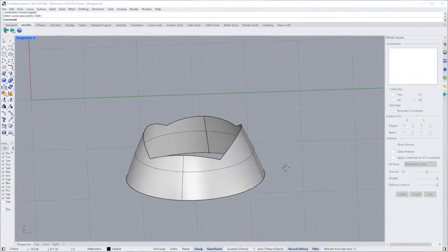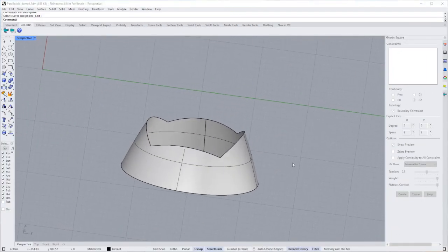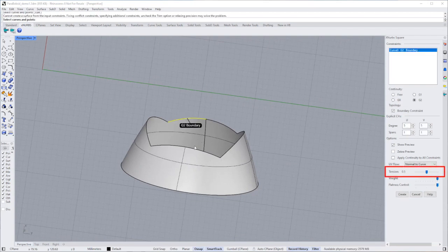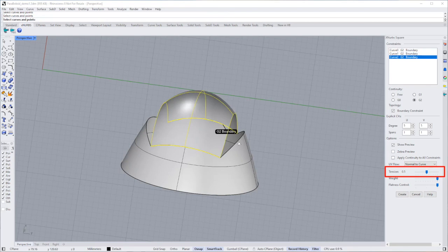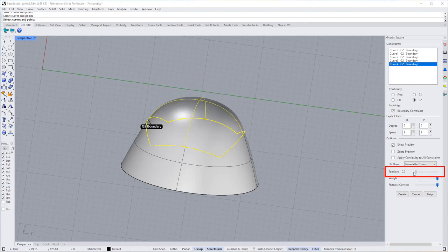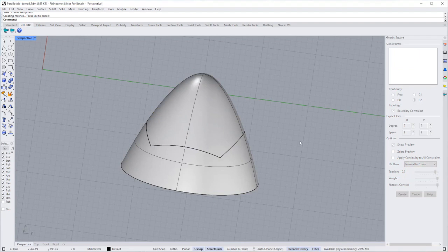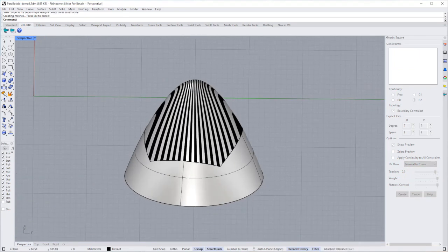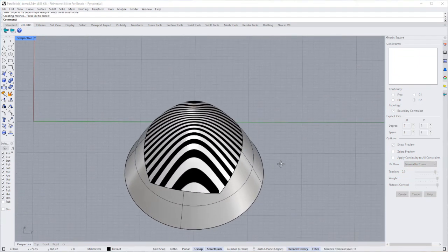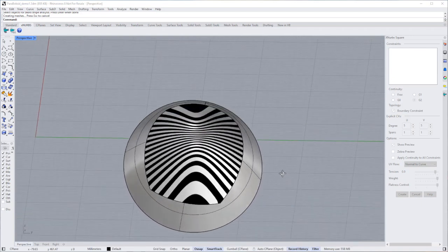Version 7 adds a tension option for square and xNURBS command. When specifying G1 or G2 for an edge, it controls the influence of the edge. You can use it to adjust the shape of the generated surface or the surface bulge. xNURBS is super fast and all regenerations are done in real time. Generally, you should use the default setting for the tension slider because the default tension setting is a reasonable or optimized value. Only change it if the default tension does not generate the desired surface.